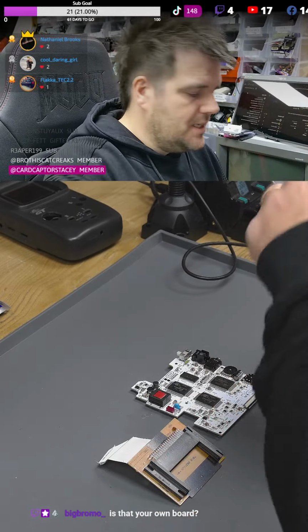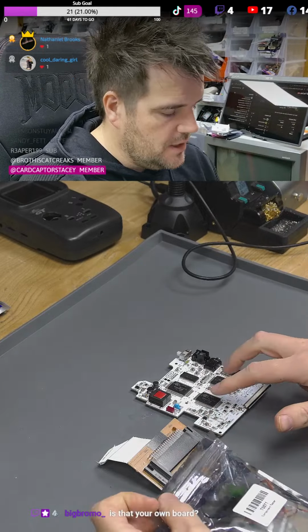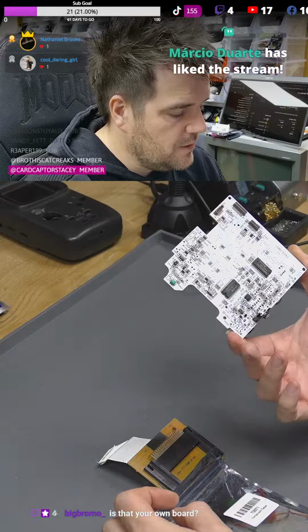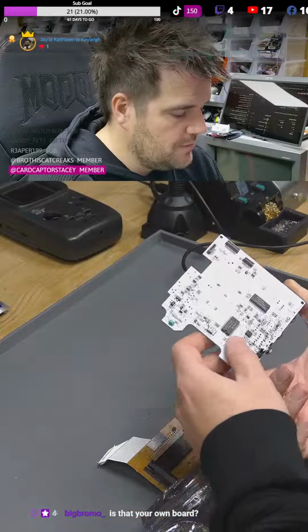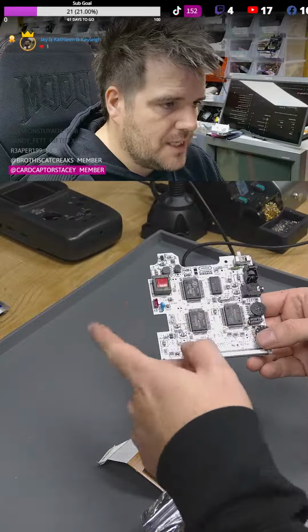So we might still have issues, or all of the issues might have purely been the PCB being bad, because we've tested every resistor and cap on here, so we know they're all good because we've measured every single one. So that's a positive. We've measured every single transistor. The only one we found faulty was one down this corner, which isn't used because he's having a backlight screen.